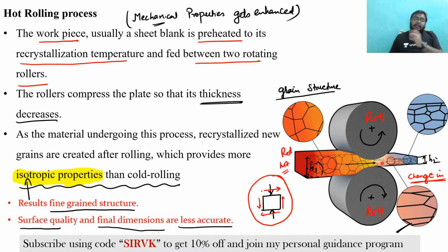Whenever the temperature is high, its ductility will be more, so the metal will flow. When ductility is more, the metal flows. So to give a proper direction, or to make any close tolerance objects, it is difficult to handle that flowability. Hence ductility will be more, so we cannot control its accuracy. We do not have control over its accuracy. This is the first thing.